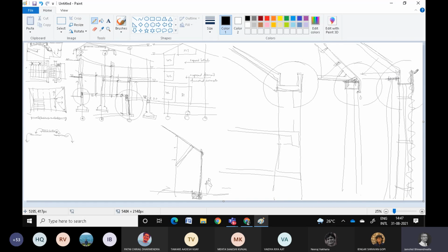And should you have a false wall or a false facade, then in between that you can always accommodate a gutter and allow the water to pass through from in between the walls. I hope this is very clear to everybody. Gutter details, please understand, how is this project going to end? This project is going to end whereby you will cut sections and be in a position to detail out sections from various parts of your building.